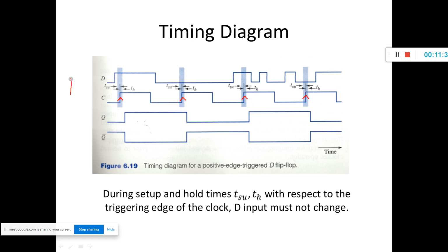So in the function table we have shown it like this: positive edge 0 to 1, positive edge. So this is positive edge. So when D is 1, when clock is at the positive edge, D is 1, so it is transferred to the Q. Next it will retain up till the next positive edge. So when the next positive edge comes, D is 0, so Q became 0 here. It will retain 0 up till when? Up till next positive edge.